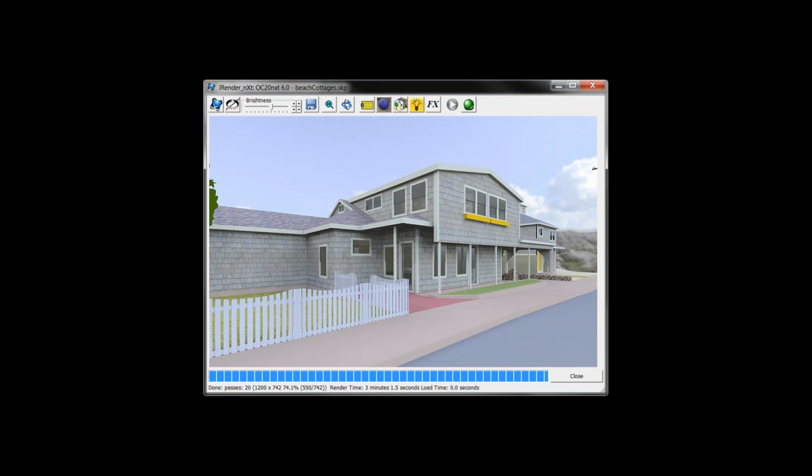And when I do, now instead of the SketchUp sky, which is just bright blue, I get lighting generated from the HDR image. A much more interesting rendering, because now instead of just blue reflected in the windows, I get clouds from this HDR image reflected. Much more realistic.